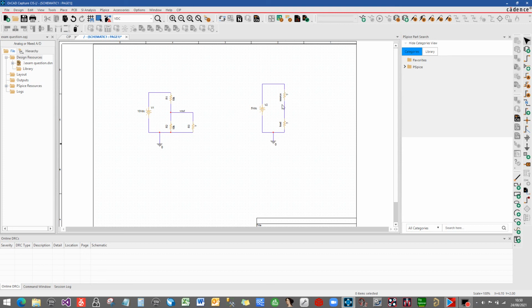Okay. Now, to find this resistance, or the Thevenin resistance, if it's a voltage source, you short circuit it. So if you short circuit this voltage source, that point is the same as that point. So basically you've got R1 and R2 now in parallel. Two 10k resistors in parallel would give you 5k.